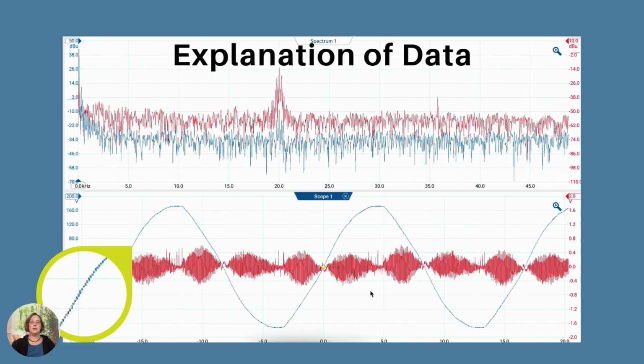I measured all the systems at the closest outlet to the inverter. All other circuits were off. The circuit for that outlet had to be on, but nothing else was running on that circuit. I measure the inverter and battery by just turning on those circuits. For each system I measured, I'll show the baseline coming from the power company first. Then I'll show the signal with the inverter running and another with just the battery, if there is one.